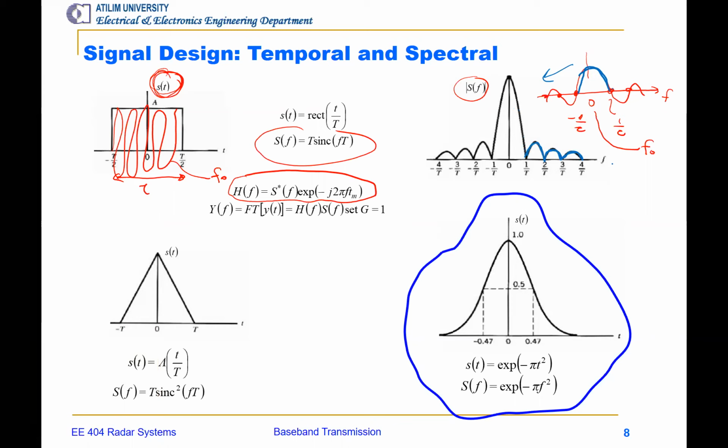Their amplitudes decay with the frequency, but it goes to infinity, okay? Which is a problem, because if we are interested in the range of the frequencies of the signal, in order to recover the signal, we have to design a receiver which covers all the frequency components in this range, which is impossible as the signal spectrum goes to infinity.